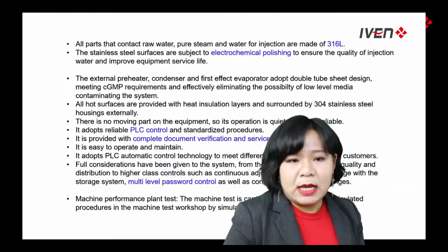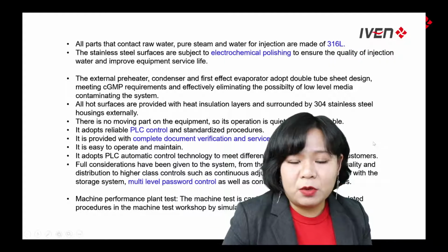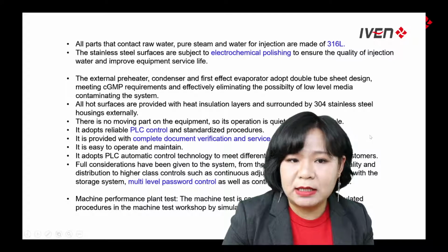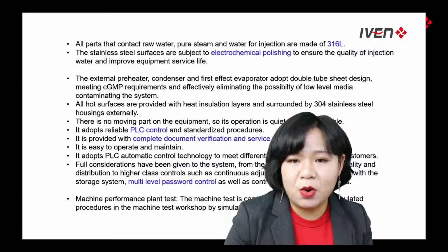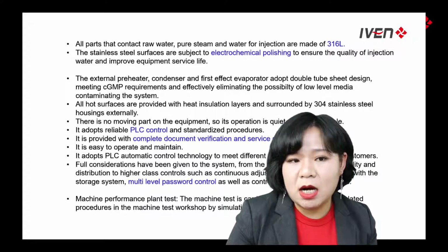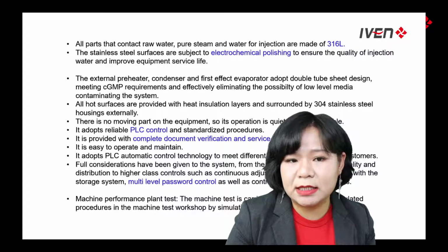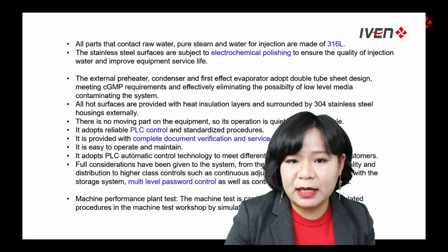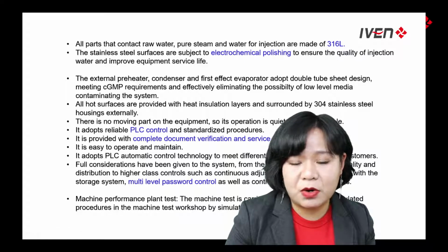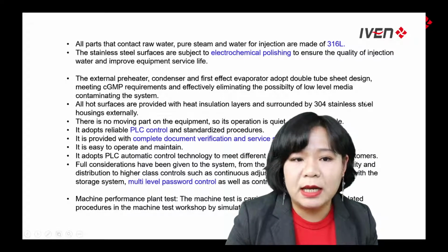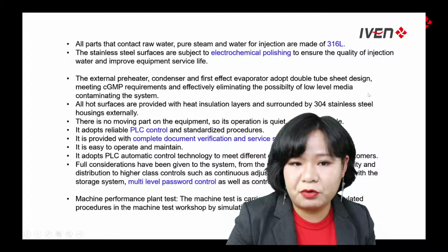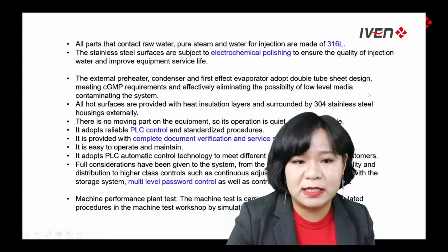Okay, all parts in the WFI water distiller machine that contact raw water, purified steam, and water for injection are all made of 316L. The stainless steel surface is subjected to electrochemical polishing to ensure the quality of injection water and improve equipment service life.